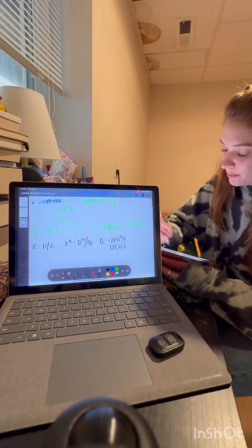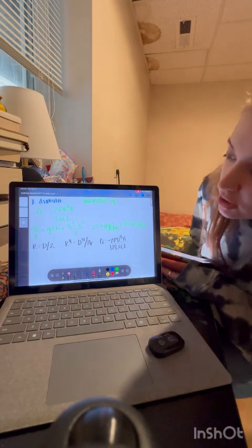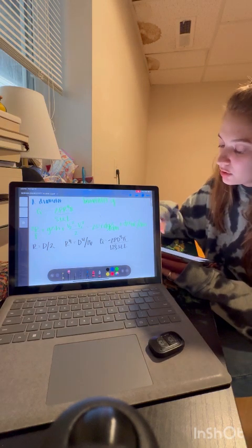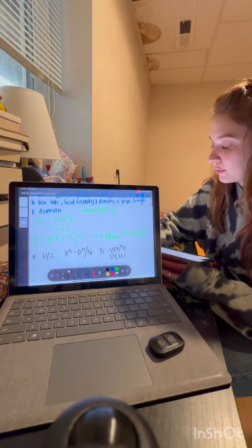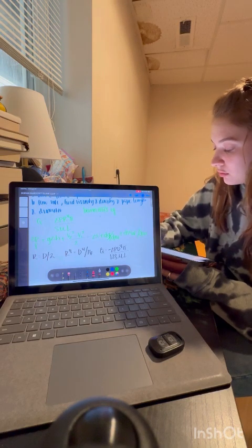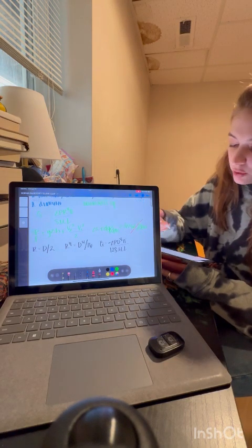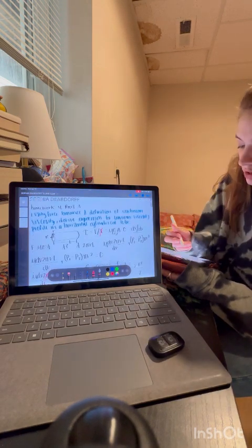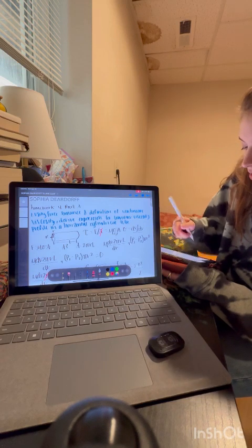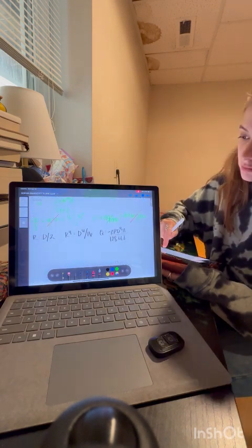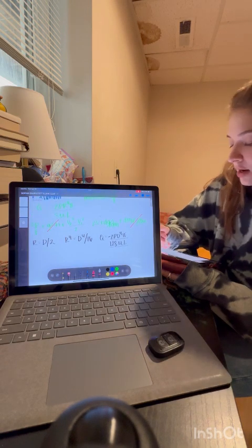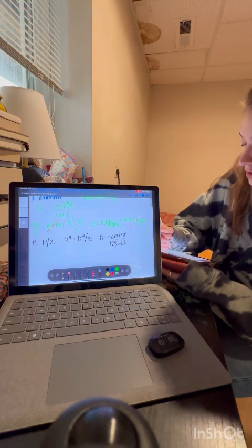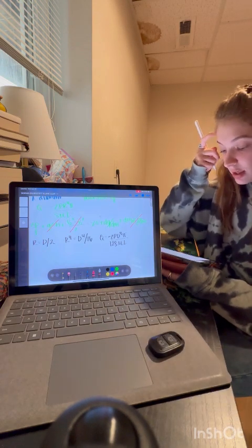And then from here, I'm going to backtrack and look at our Bernoulli's equation. We know that there is actually no work added to the system from non-flow, so we're going to be able to cancel that. We know that there's no change in height from our picture that we drew in question 1. There's just the distance L. We also know that for our velocities, we will choose points where velocity is equal to 0 to make this simpler, so we can get rid of that as well.